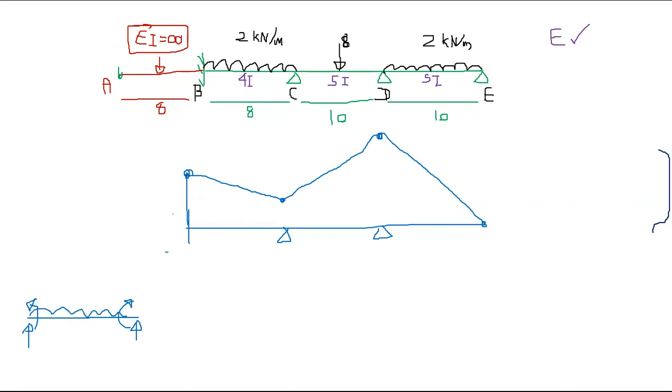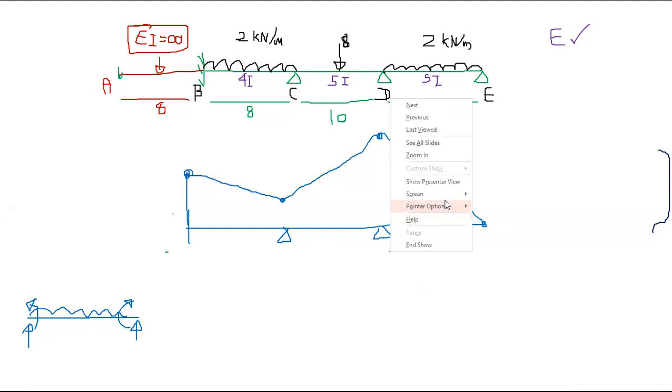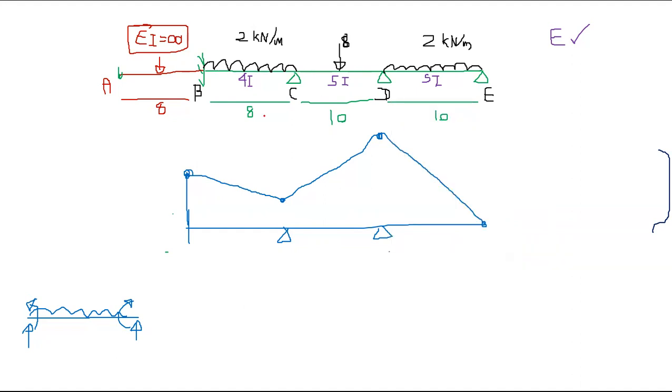For example, you can determine the shear forces if you want, right? So to construct the full bending moment diagram, you need to consider the simply supported bending moment. So you have a UDL, so you will have a curve like this. This is a point load, you will have something like this. In my moment distribution lecture, please watch it, I have explained this clearly, right? How to draw this.